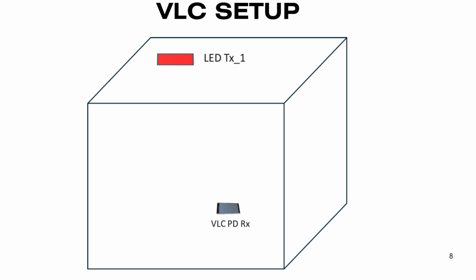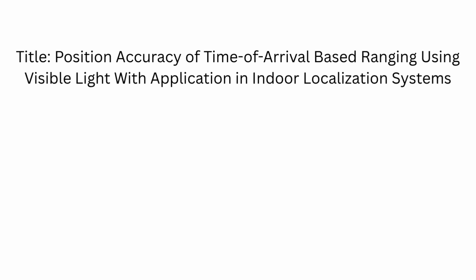One of the papers also discussed the responsivity of the receiver and validated that the silicon-based photodiode responsivities are around 0.2 ampere per watt at around 400 nanometers wavelength, while 0.6 ampere per watt at the peak. I have also added that paper title, so you can give it a read at your convenience.